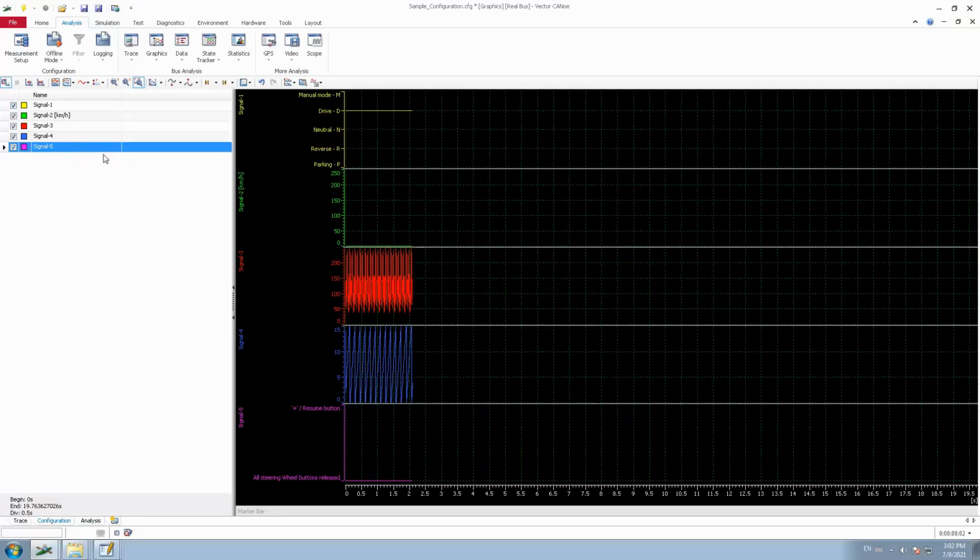Coming to the options, the first option we will see is the toggle signal legend. This particular panel is the legend part, where you will find the signal details, the signal root path when you hover on each signal, and its current values. And on the right side, it's the signal plotting for the corresponding signals, whatever you've selected over here. So you will see the variations of the signals on the right side, and you will see the current value on the left side.